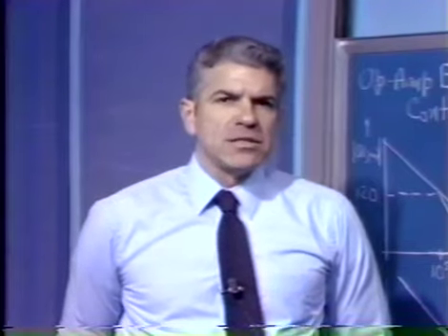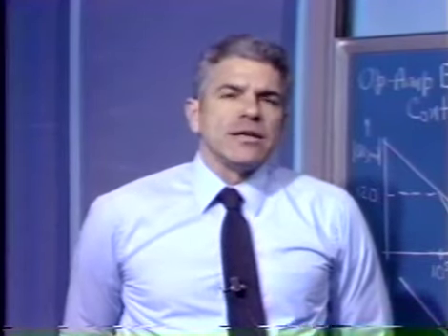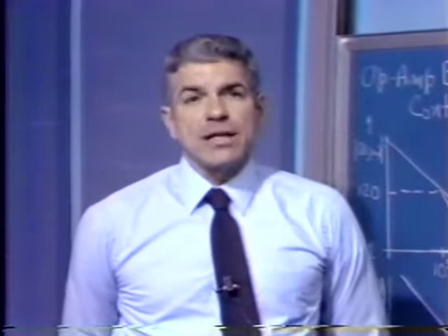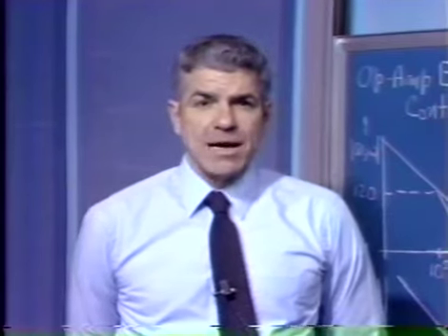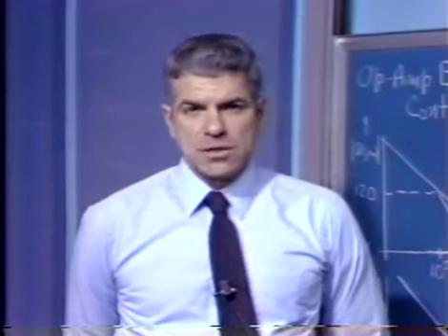Another problem exists in that kind of a loop in that the gain, the loop transmission in these sort of gain control loops is always a function of operating conditions. It's a function of the amount of gain control that's present at a given moment. And so here you have a loop that has two uncertain variables, one the location of a pole, another one being the loop transmission magnitude.